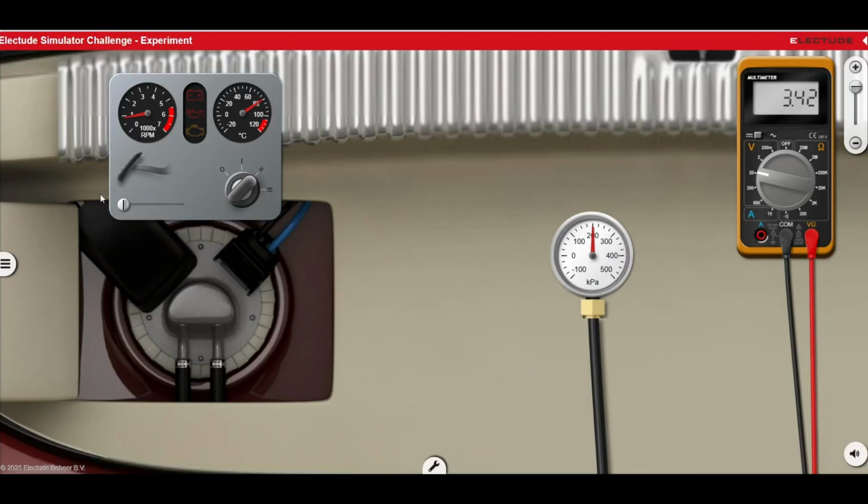Yeah, I think we've played with that. And you see the voltage here is increasing a little bit. That means it will take a long time to get back to zero, but at least this increment is showing us that this is an NTC. When the temperature starts falling, the voltage increases. That's the point. And let me switch this off and wait.